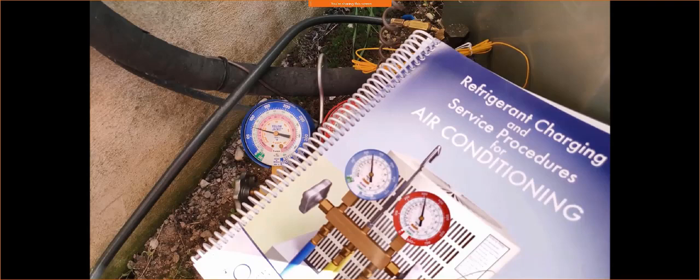One big thing too is the airflow. We want to make sure that all the registers are open throughout the house, all right? People have a tendency to put stuff on there, close them off, thinking, hey, I'm trying to direct airflow somewhere else. Well, you do that too much, you're going to have issues. I had one customer, he's like, hey, my system keeps freezing up. I'm like, okay. So I head out there, and it's a brand new system, about 2 years old. He shouldn't really be having issues with it, but he is.